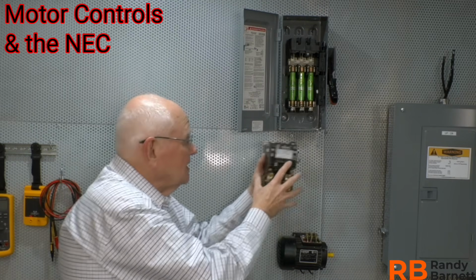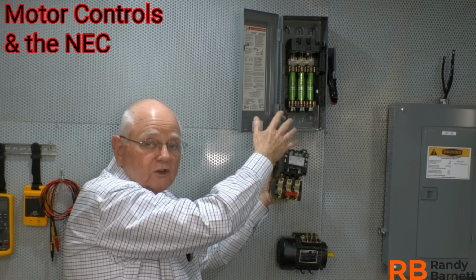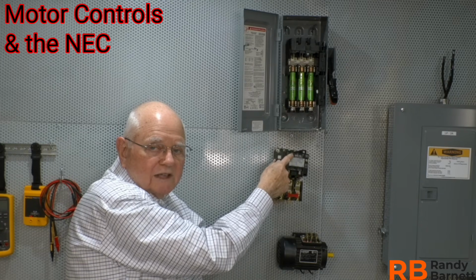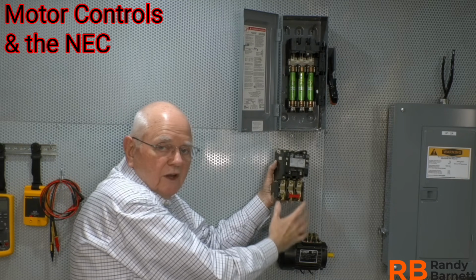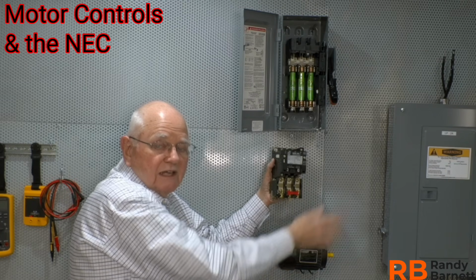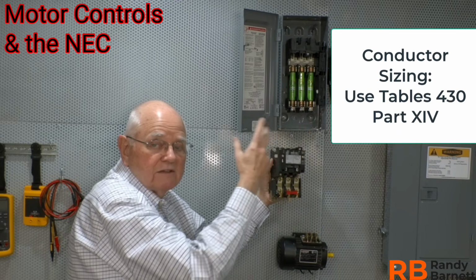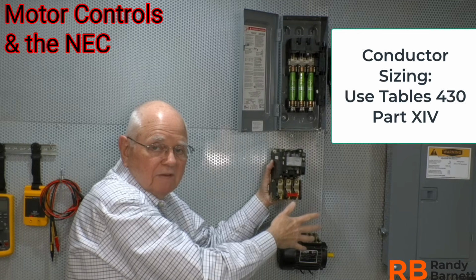The power comes in from wherever, goes through the fuses for short circuit and ground fault protection, through my starting contactor. When I close the contacts, power is supplied through the overloads down to the motor. The overloads are sized based on the nameplate data of the motor. To size the conductors, I go to tables in Article 430. Given the certain voltage, phase, and horsepower of the motor, that's how I size my conductors.